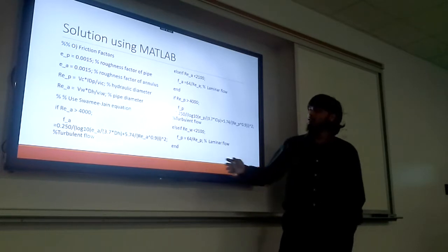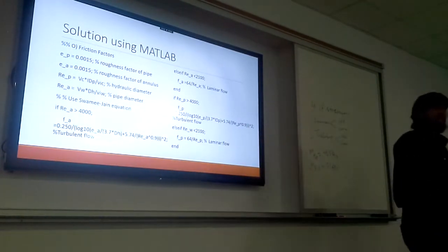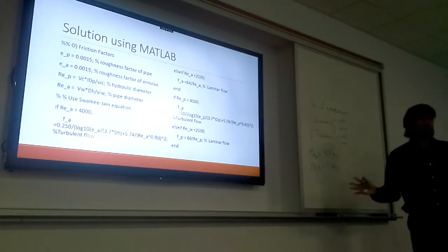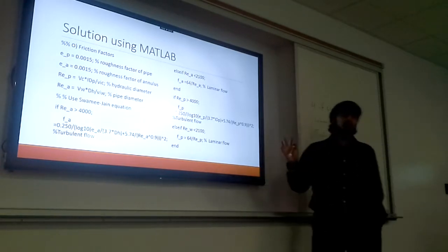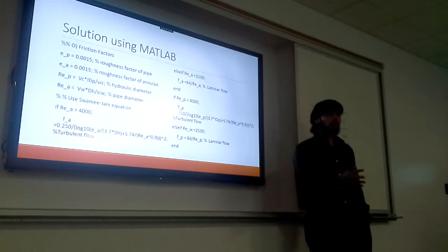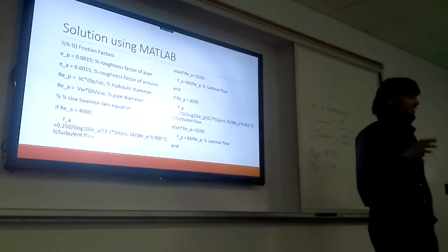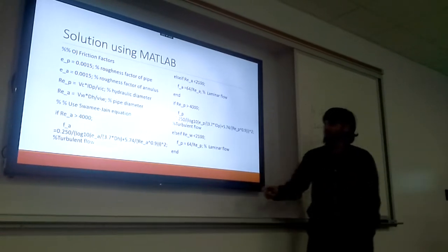And I decided to use the Swamee-Jain equation, but you can use whatever equation you want. There's the Chen equation, Allen equation, Churchill equation. It's up to you, whichever you want. I have no problem with it, as long as you use something that's authentic and reliable. So don't go look at someone else or come up with your own equation and use it. That's not going to work. But go ahead and apply that.